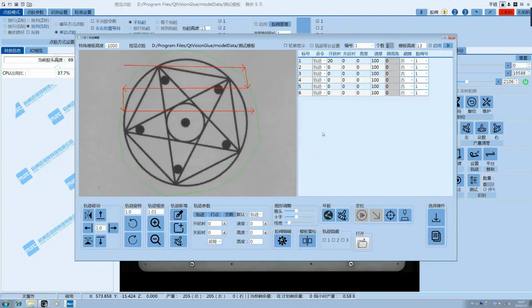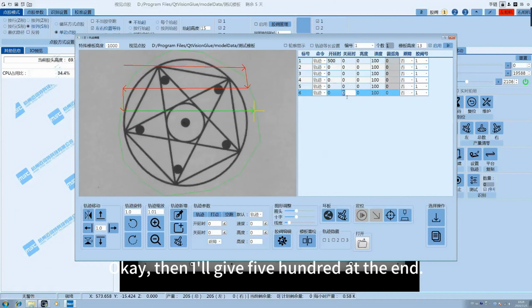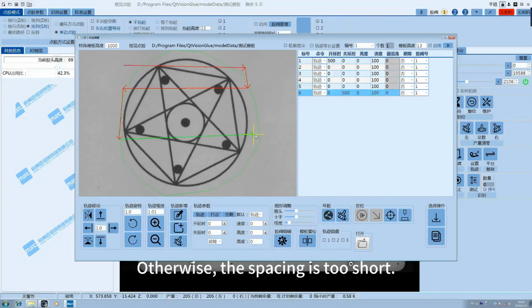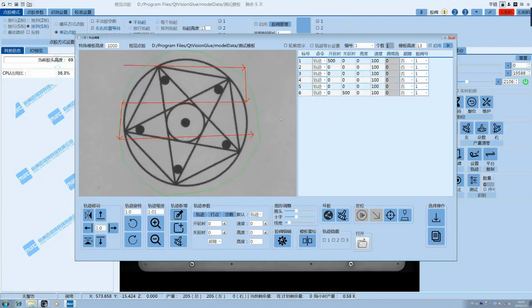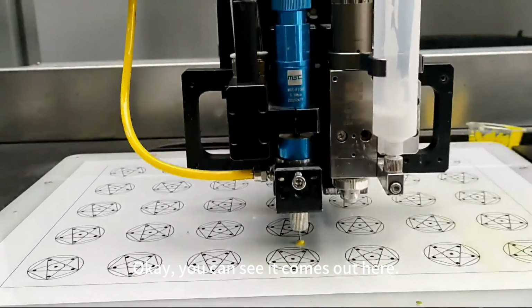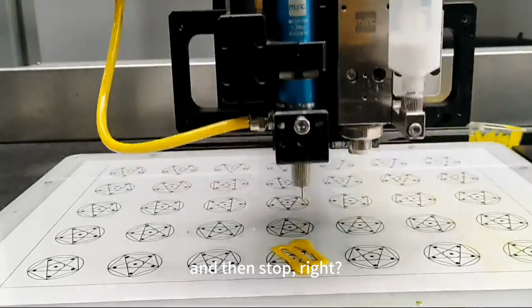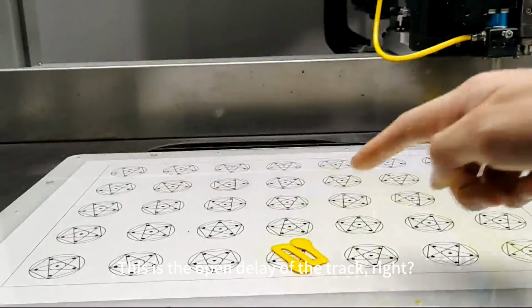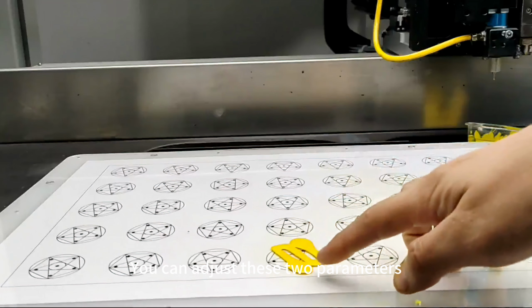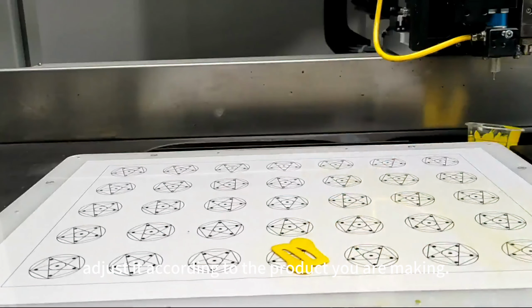That's it, and I can show you that. Let's delete it first. Then I'll give a little more for this, and give 500, so it's obvious. Okay, then I'll give 500 at the end so that everyone can see it clearly. I'll pull it longer. Otherwise, the spacing is too short. Okay, you can see it comes out here, stop, right? You can obviously see this is the open delay of the track, right? There's a lot of glue. And here's the off delay, coming out with a lot of glue. You can adjust these two parameters according to the product you are making.